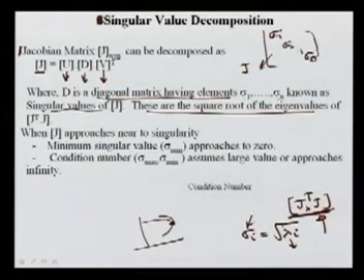One eigenvalue will be 0, and this sigma min will have 0 value. So it approaches 0 once J approaches singularity. This singular value gives information about how much your system is operating away from voltage instability, that is, how far away from the nose point.